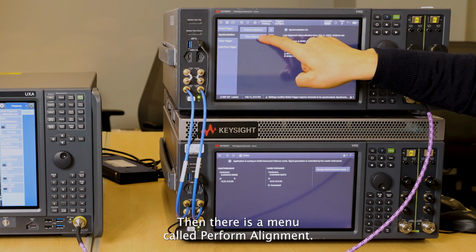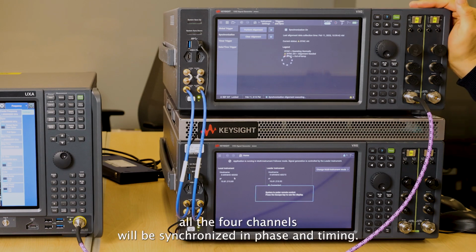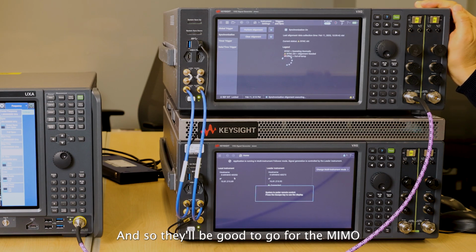Then there is a menu called perform alignment. I just press this button. So now all the 4 channels will be synchronized in phase and timing. And so that'll be good to go for the MIMO application.